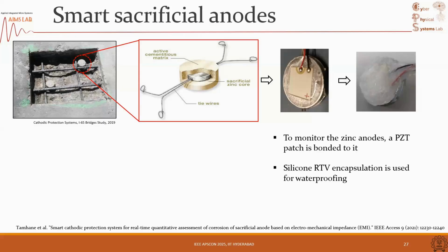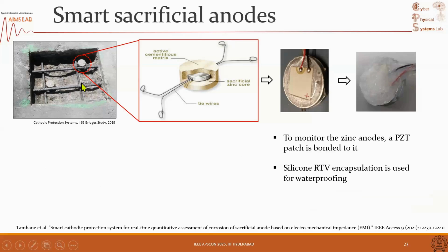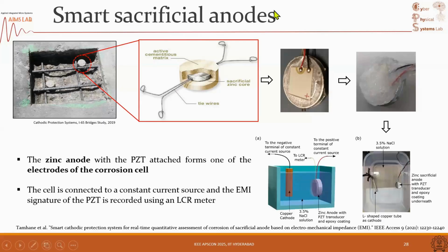So in construction, you can use the sacrificial anode. They are called sacrificial because that rusts but protects the steel from rusting. So in that sense, it's sacrificial, and it's the anode in the electrochemical reaction. That's why it's called a sacrificial anode. All it is is a zinc disc that is tied to the reinforcement with galvanized iron wires, so that you establish an electrical connection. The zinc corrodes, the steel does not corrode. And you have to put an electrolyte around it, which is a conductive mortar. So the conductive mortar works as the electrolyte.